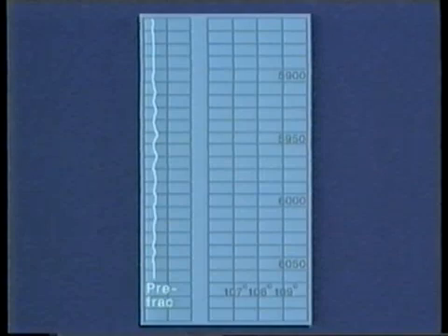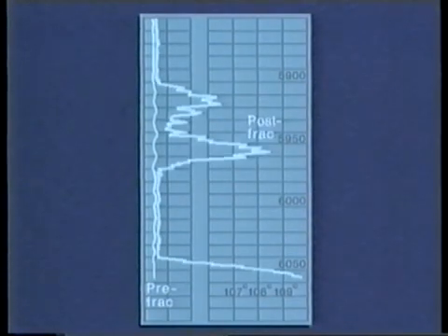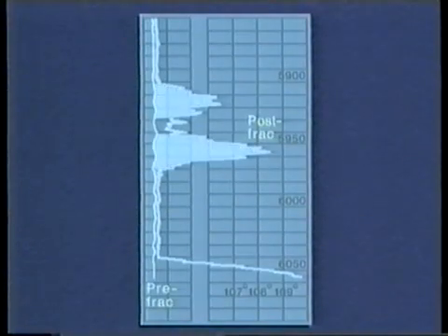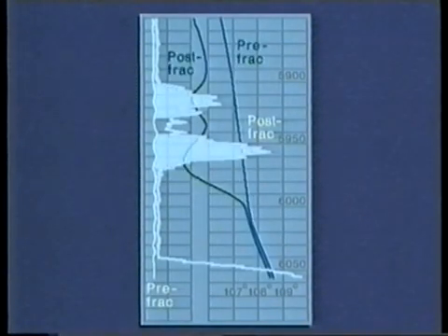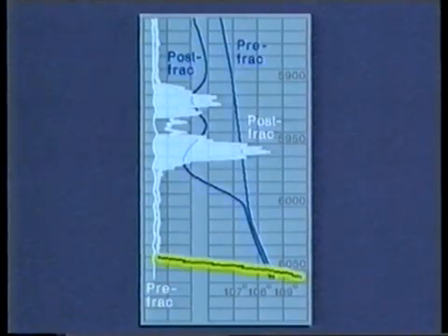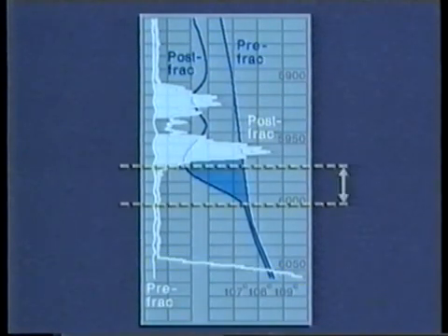Fracture height determinations are made by tagging the injected proppant and then comparing pre- and post-fracture gamma ray logs to detect its location. A pre- and post-fracture temperature survey confirms the fracture location. The increase of radioactivity at the bottom of this interval is attributed to the settling of proppant in the rat hole. The apparent discrepancy between the temperature and tracer techniques at the bottom of the fractured interval may be caused by the responsiveness of the temperature survey to the gross fracture height through which the fluid moved, part of which apparently remains unpropped.